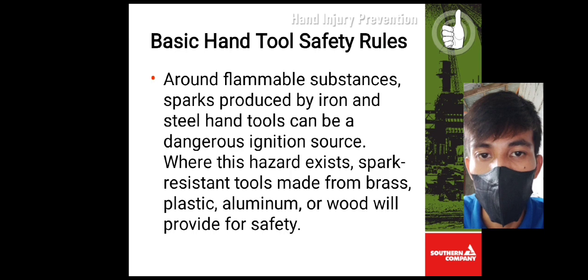Basic hand tool safety rules. Around flammable substances, sparks produced by iron and steel hand tools can be a dangerous ignition source. Where this hazard exists, spark-resistant tools made from brass, plastic, aluminum, or wood will provide for safety.